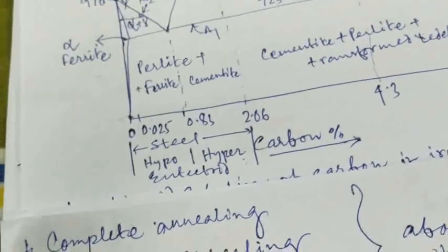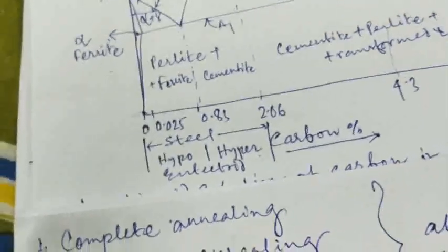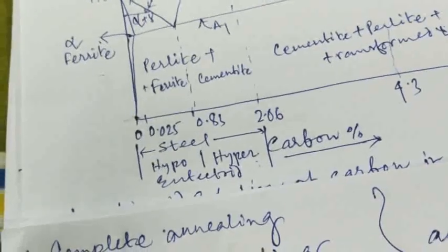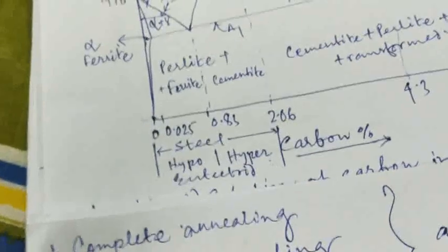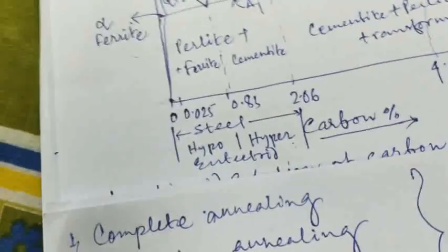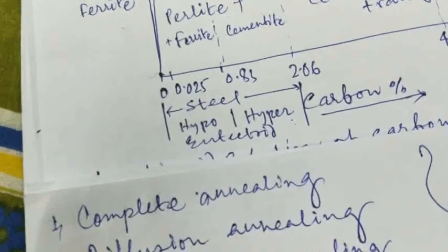If there is reticular cementite in the hypereutectoid steel, it is necessary to eliminate it by a normalizing process before the spheroidizing annealing, so as to ensure that the spheroidizing annealing is normal. The objective of spheroidizing annealing is to reduce hardness, make the structure uniform, improve machinability, and prepare for quenching.